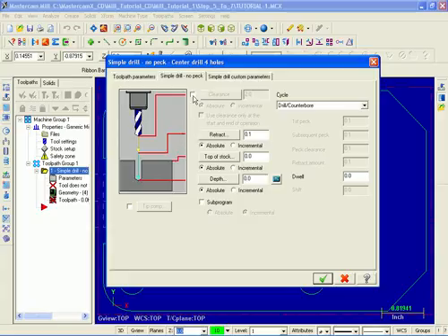First thing I'm going to do is turn the clearance on. It's set to absolute and the value is 2 inches. Moving on down, I'm going to put a check mark against use clearance only at the start and end of operation. My retract is in absolute, set to 0.1, that's good. Top of the stock is 0, and that's also an absolute. Depth is an absolute, and I'm going to set this to minus 0.15. Everything looks good now, so I'm going to go down to the bottom and pick the OK button.